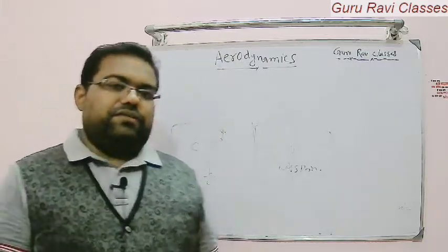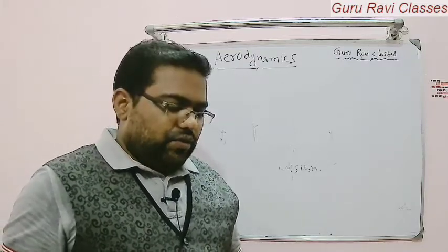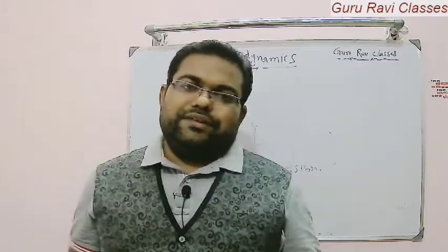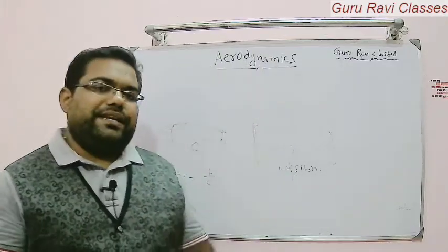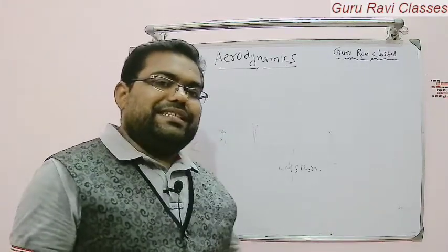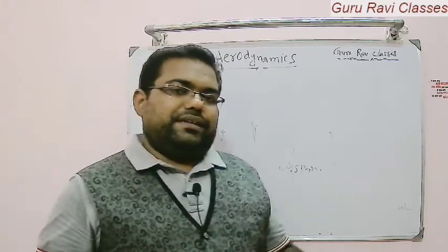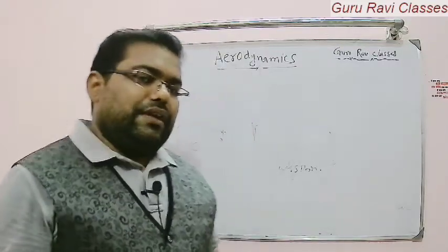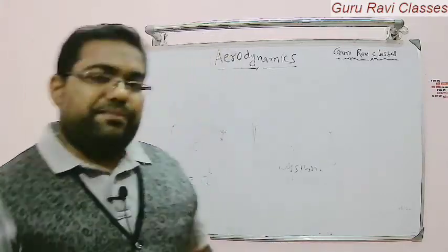So for different aircraft, the wing aspect ratio will be different. It will be varying between 6 to 16, right? If we are going for sports aircraft which have a rectangular wing, their aspect ratio may be nearby 14 or 12. If you are going for a fighter plane, where we need a very compact design, aspect ratio will be between 6 and 8. And for general aviation aircraft or sports aircraft, we are basically using a larger wingspan, so the aspect ratio will be more. That will be ranging between 10 to 16, maximum 16. Beyond that you cannot go.